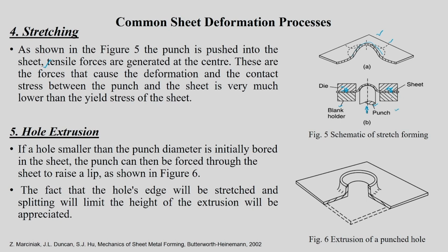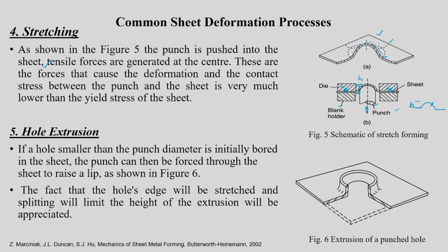It can also be used as a material testing method. You can use this as a formability test, to see, let us say, what is the height of deformation. Let us say this is the height. For example, what is the height of deformation at which you have a fracture in this location? That can be used as a measure of sheet formability. That can be discussed with respect to this figure as h, let us say, this height of forming. More complex details are going to come in future, but I am just giving you an idea here.